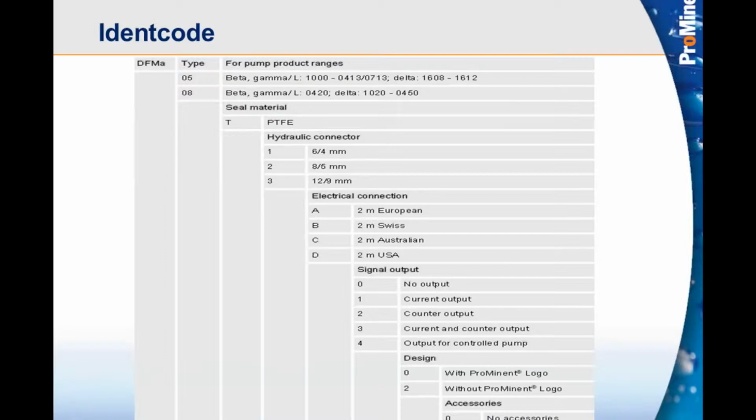The device does like to see that pulsing type flow, which is good because that's the flow that our pump is creating. So we have to be sure that we install it prior to the pulsation dampener. It actually needs to see that pulse going through. Most of the other selections are pretty much standard according to pump data or system data, as far as the tubing size we're going to use with it, the electrical connection.